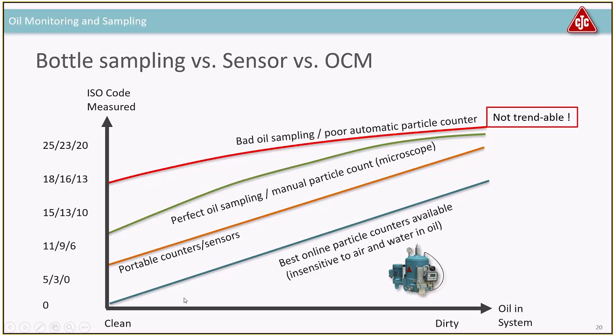And is that incorrect? It's actually not. It depends, of course, on the system. But I've seen some, like a hydraulic pitch system on a wind turbine. It only had 250 liters of oil, and the filter was circulating 250 liters an hour. So you are circulating the full volume of the oil in the system every hour.